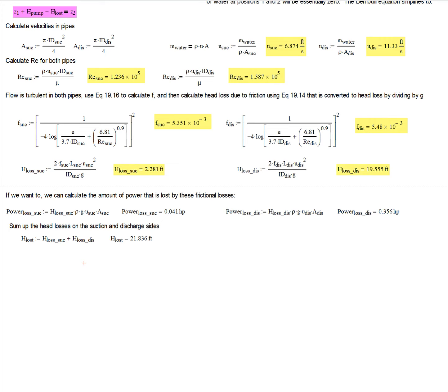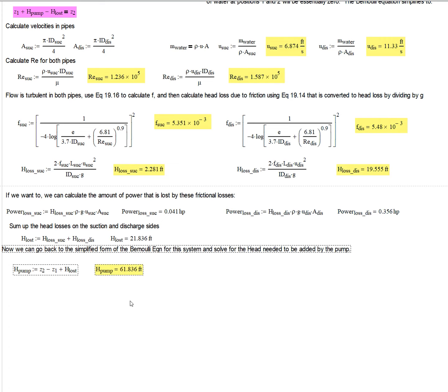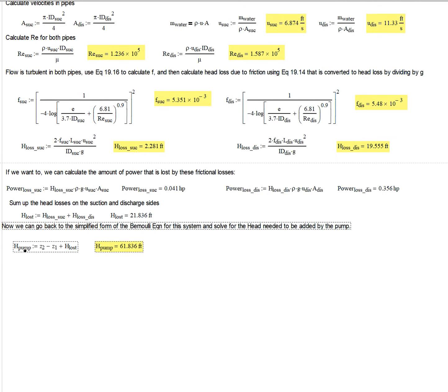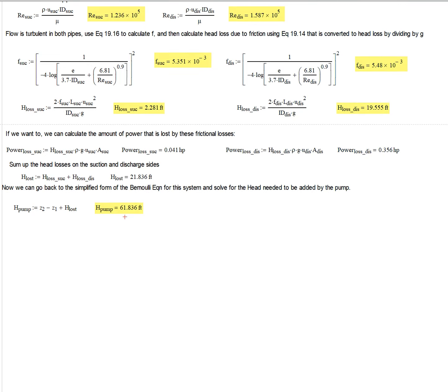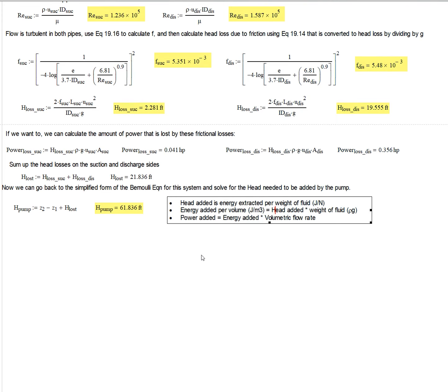We've got our elevation changes, and so we can go ahead and calculate this. Solve for the head that's required for the pump, and that's 61.836 feet.